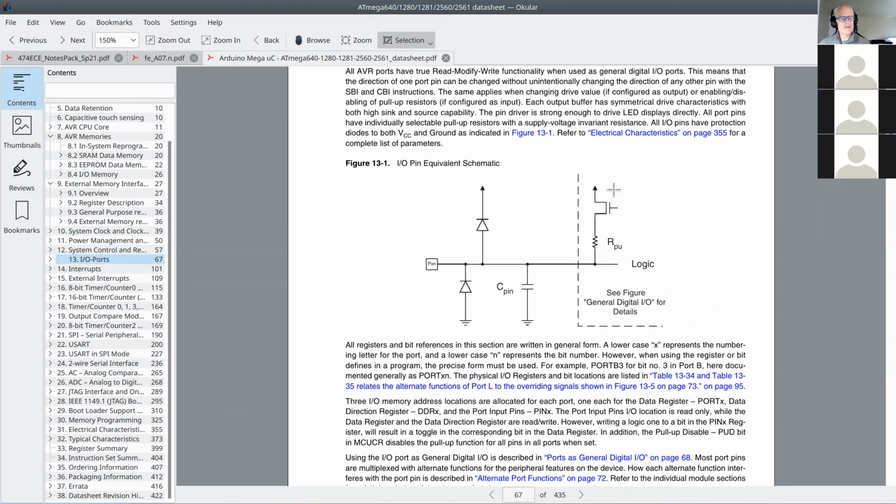That will destroy this logic, except the diode conducts, it's now forward biased. And so the highest this gets to is 5.7 volts, the forward bias voltage of the diode plus the 5. So hopefully this is protected at 5.7 volts, it's still safe. Similarly, if you go to a negative voltage, this diode protects your input.